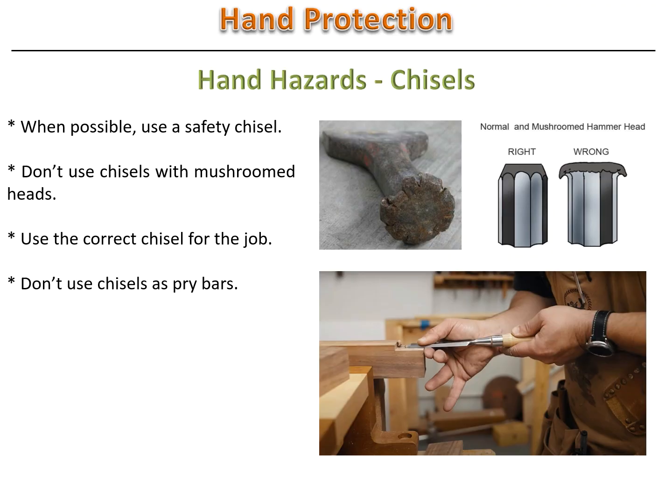Hand hazards, chisels. When possible, use a safety chisel. Don't use chisels with mushroomed heads. Use the correct chisel for the job. Don't use chisels as pry bars.